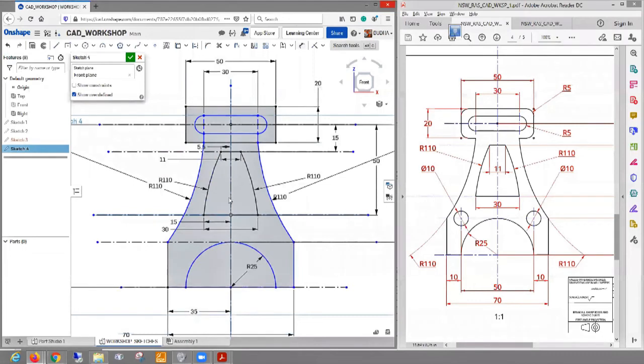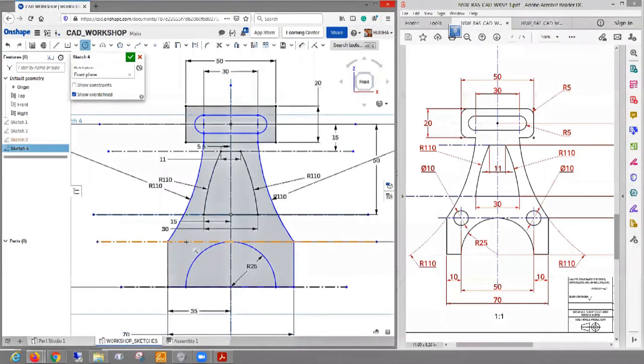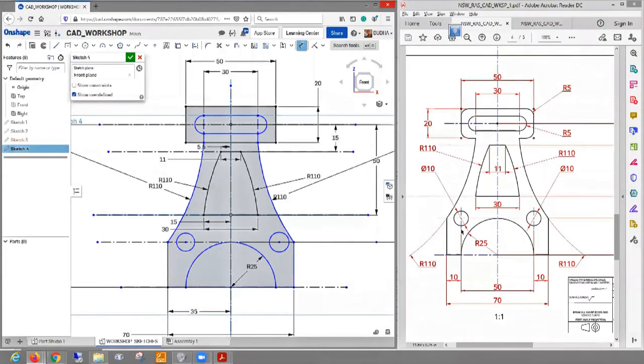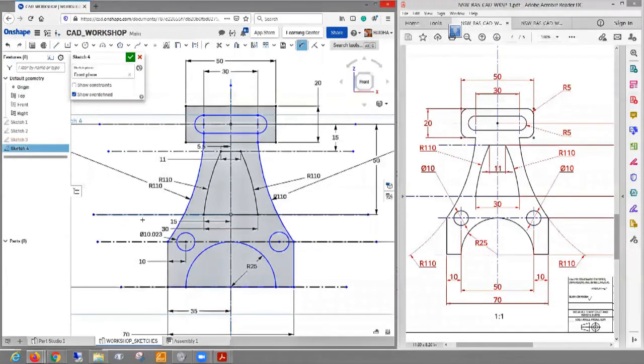Create a circle over here and over here, but we need to make sure that the center points are a known distance apart. As you see, this center point is 10 apart from one of the sides, the closest side. We will set that to 10. Make sure that the diameter is what is required. The diameter is also 10.